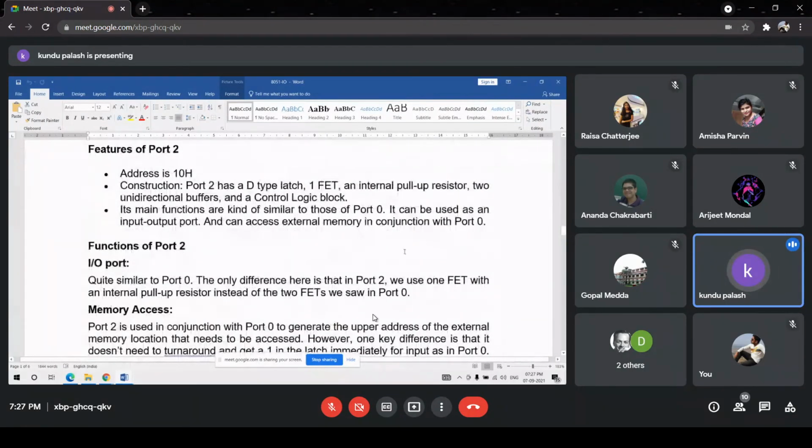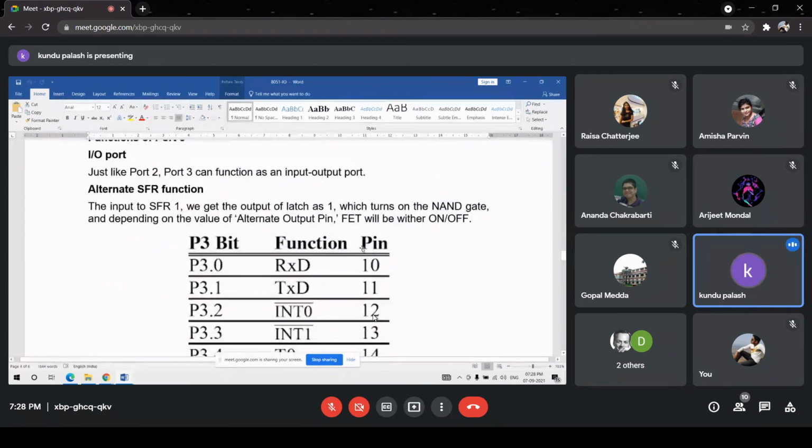Now, eventually we will see why the floating logic is required for a microcontroller. An interfacing circuit may operate with a power supply voltage of a different value, not 5 volt. It may operate with 15 volt or 32 volt. So when this peripheral circuit operating at a voltage other than 5 volt needs to be interfaced with the 8051, then the open collector type port is very much preferred. Otherwise, it may damage the circuit. We will discuss much more about hardware interfacing like that.